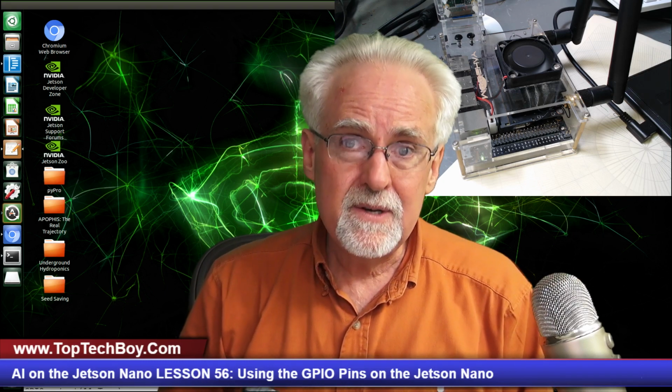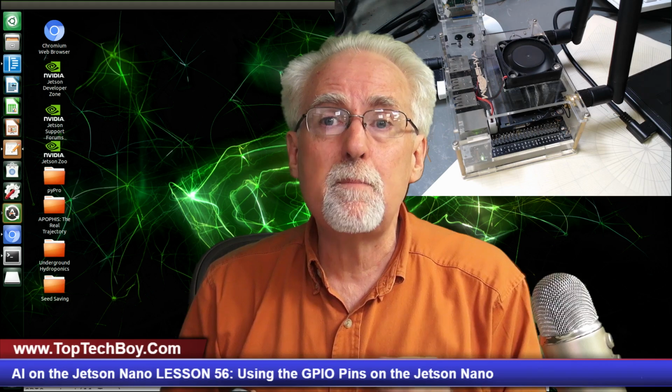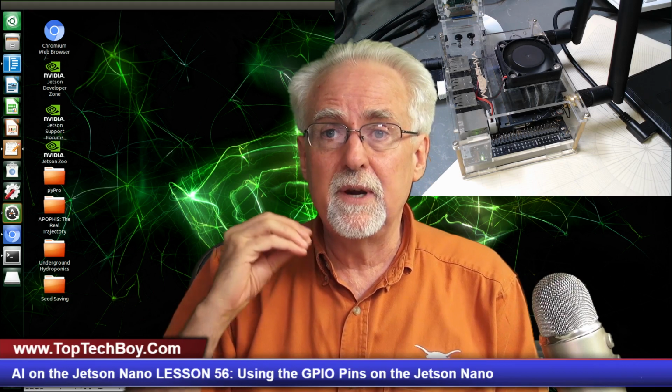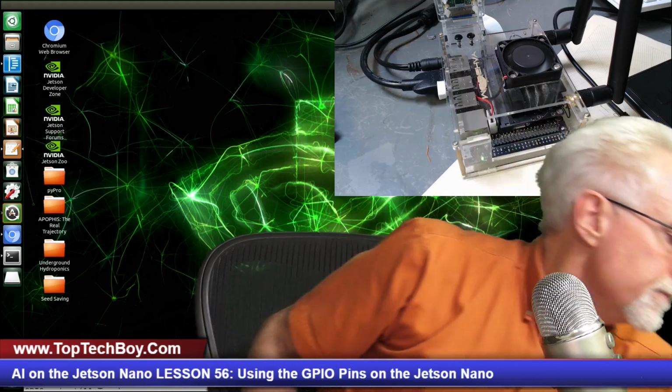Well, what I learned is that these pins are very, very sensitive to the capacitive load that you connect to them. So great big long wires like I have here with this digital voltmeter have too much capacitance, and the Jetson Nano GPIO pins are not able to drive those.